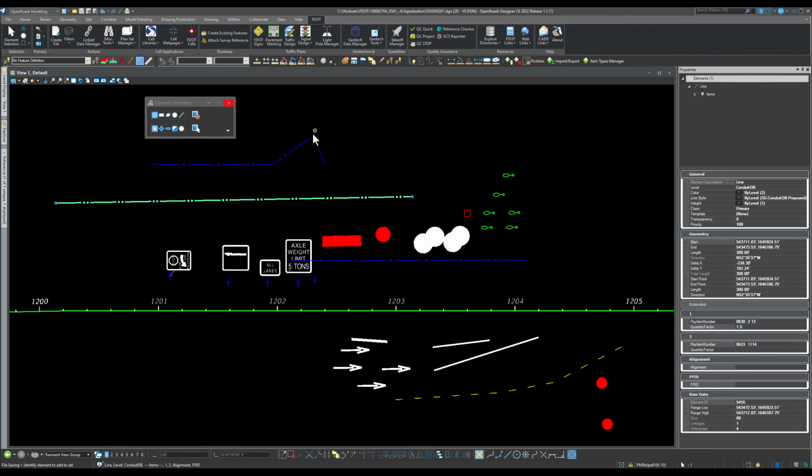These tools are just bringing the cells and lines preloaded with these items, but you can actually add the items by yourself. Just make sure your lines and cells have proper geometry, and run the Takeoff Manager, it will give that to you.